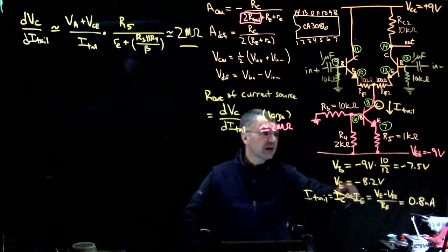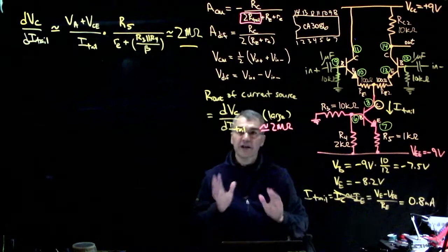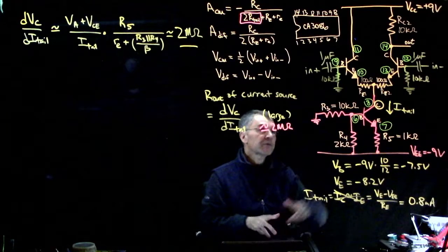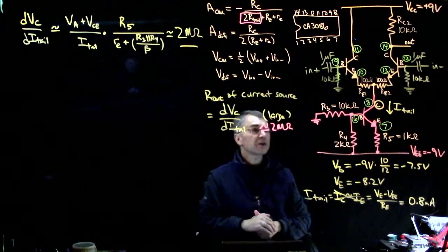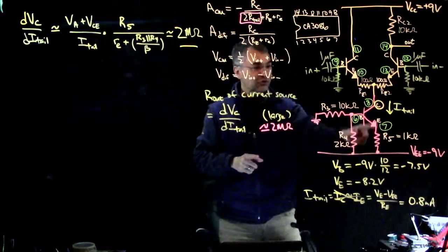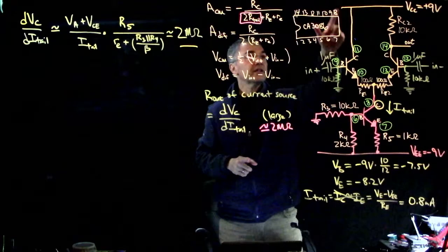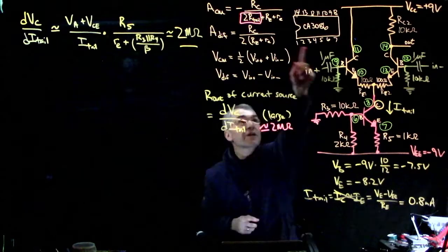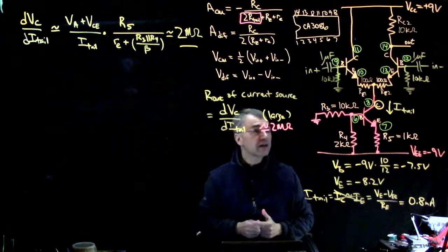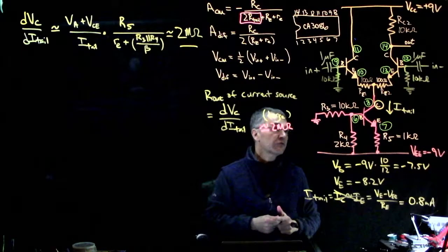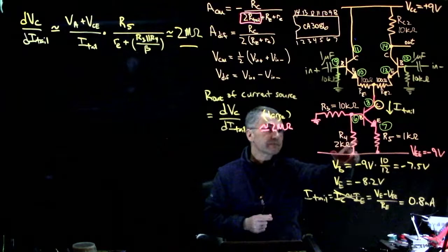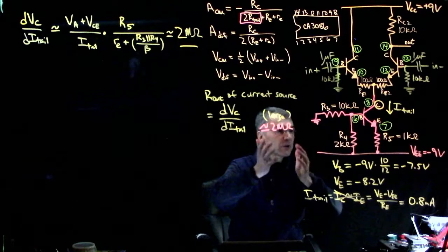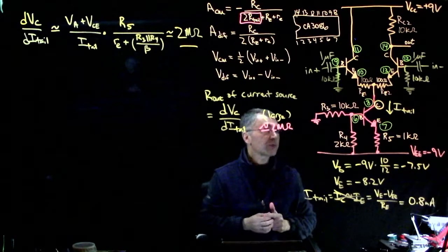Now, instead, I claim we have about 0.8 milliamps. Let's analyze that. So I wanted to pick resistor values that were sort of convenient. This is using one more transistor from your transistor array. This is pins 6, 7, and 8. So 6, 7, and 8 from your transistor array turn out to be one more transistor in this array, the CA3086 transistor array. I first kind of dreamed up what would be ideal, and then I said, well, what do we really have in the box? And this is a pretty good choice based on what we have in the kit.